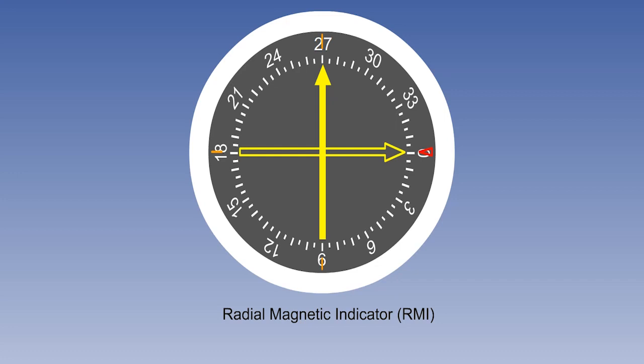If correctly synchronized, it continuously shows the aircraft's magnetic heading. In front of this rotating compass indication, there are VOR or ADF needles, or both, depending on the aircraft's navigation fit. We will assume 1 VOR pointer and 1 ADF pointer.